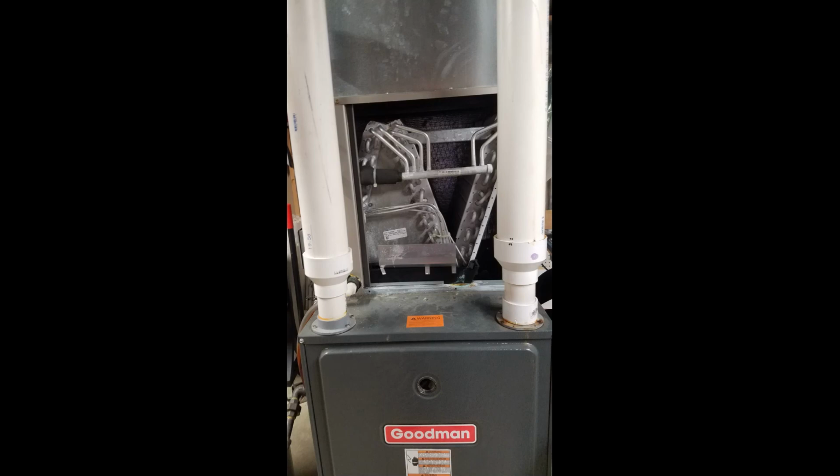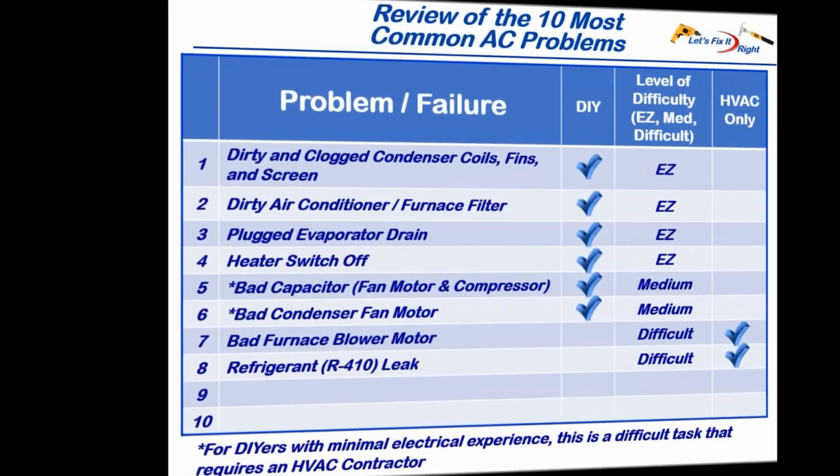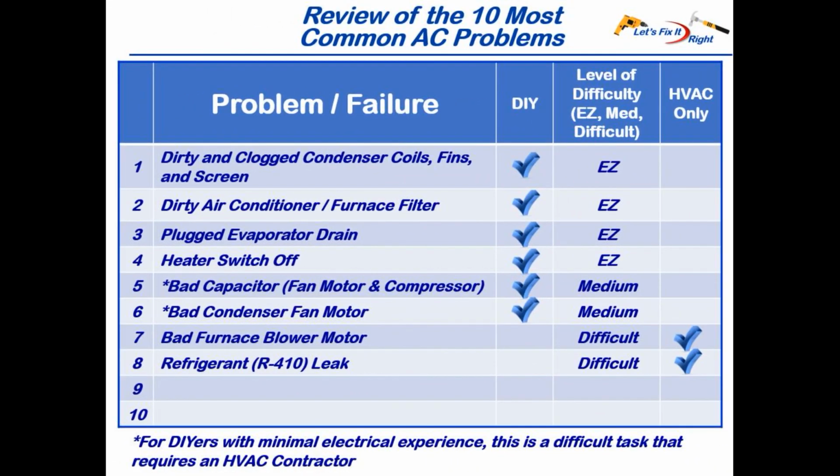Consequently, this is a very expensive leak requiring a new evaporator and a new charge of R410 refrigerant. In many cases, people opt to purchase a new air conditioning system instead of making a repair. I rate this as a difficult task that requires an HVAC contractor with special refrigeration tools and equipment and experience beyond the typical do-it-yourselfer. Considering this is an expensive repair, I recommend that you get 2 or 3 quotes from different HVAC contractors.